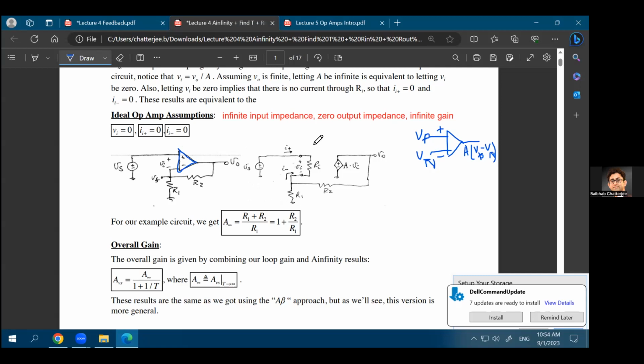Now, and again, while I'm talking about gain, it is AC gain. Again, there were probably numerous questions on the GroupMe chat on the VTC, the voltage transfer characteristic, and there was some confusion about the biasing points and the gains and so on. So I'll reiterate this again. In this course, we'll only be talking about AC gains. Amplifiers or MOSFETs or BJTs, they cannot provide you a DC gain.